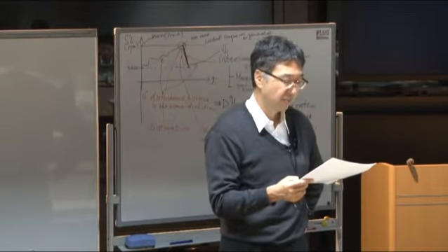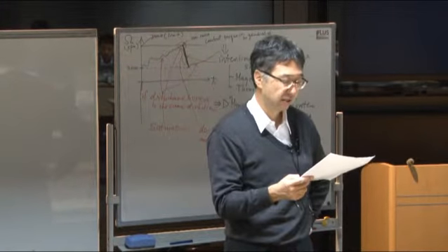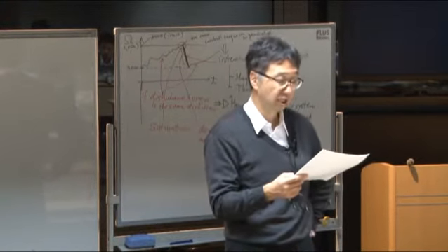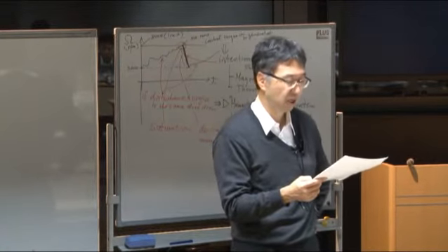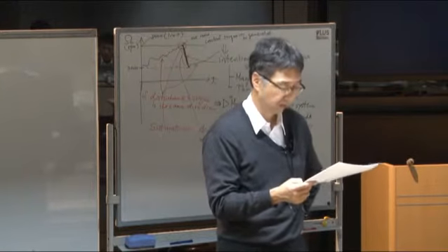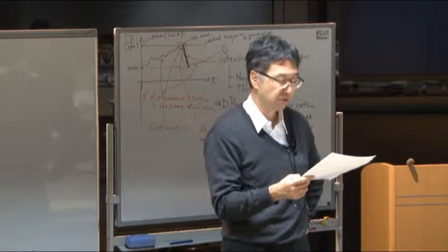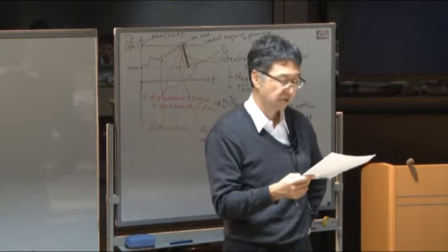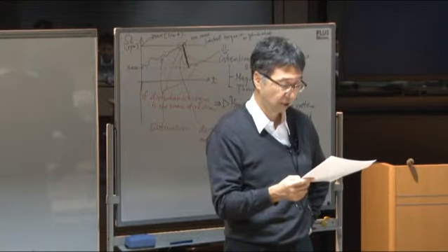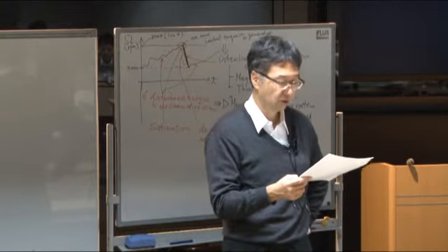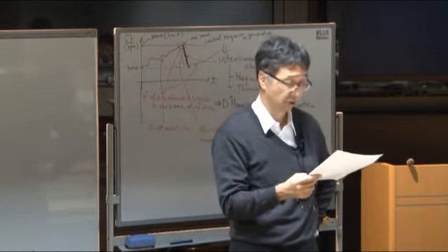Okay, and the magnetic disturbance torque. As I said, the satellite has a magnetic momentum, and it interacts with the geomagnetic field, and it gets some disturbance torque. And the gravity gradient, and the solar radiation, and the thrust misalignment. The thrust does not emit power in the desired direction, but it always has some error. And so this gives some misalignment. This gives some disturbance torques.